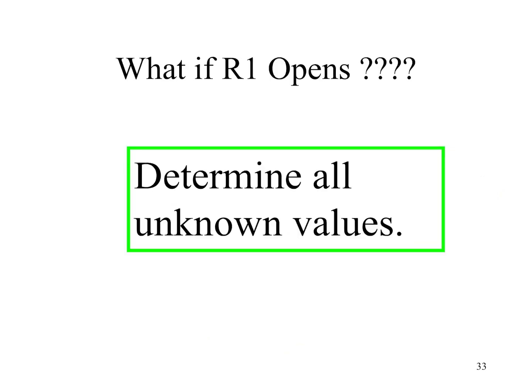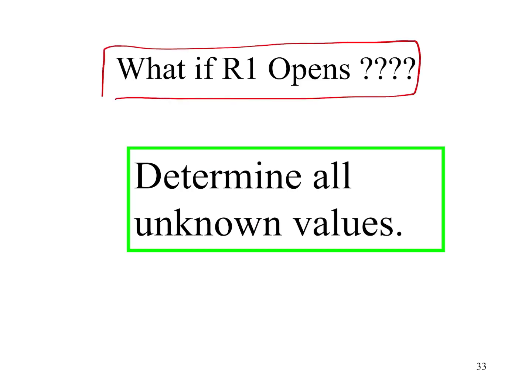Okay, so what if R1 opens? Now let's go back to our completed circuit when it's operating normally, and we're going to look at the result of R1 opening. But before we go there, what's the property of R1's opposition when it opens? R1 would now equal infinite ohms.